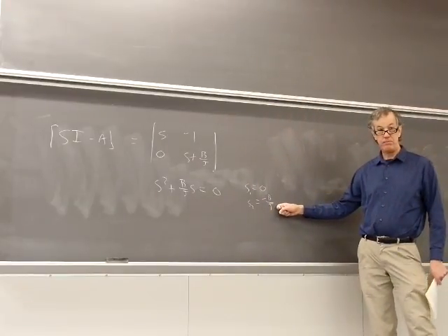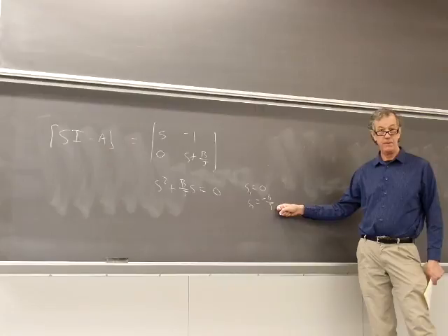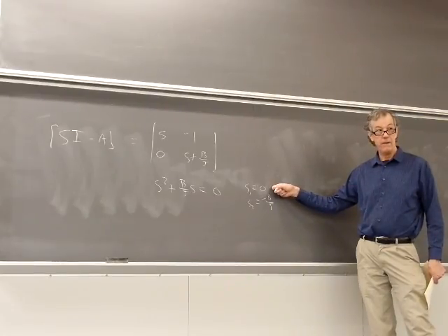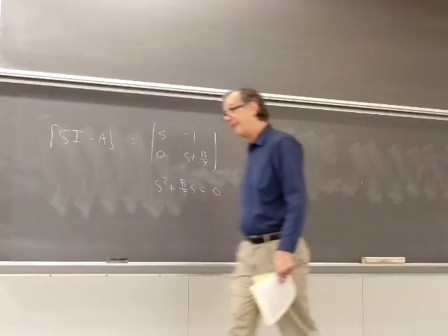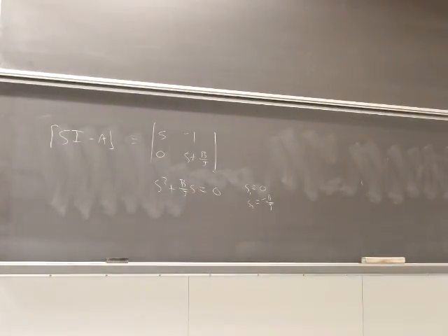This one, that root is what, stable or unstable? Stable. That root, marginally stable. Basically, it's a pole right at the origin. It may not be exactly the best thing I want for this, but it's a good step to do. But before we can design a controller, we need to check for what? Controllability and observability. Let's do that.